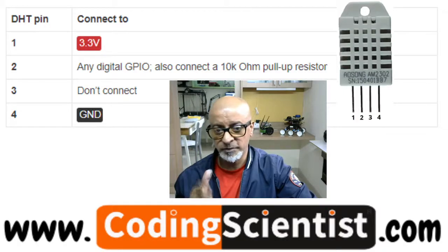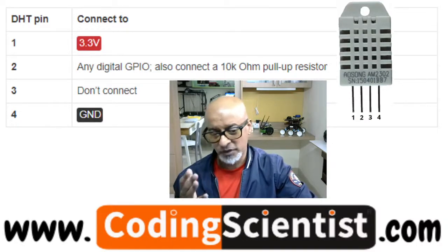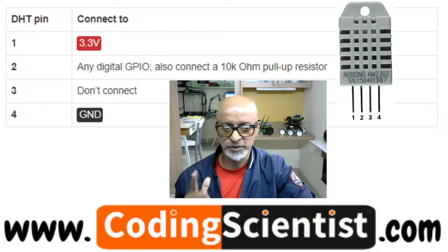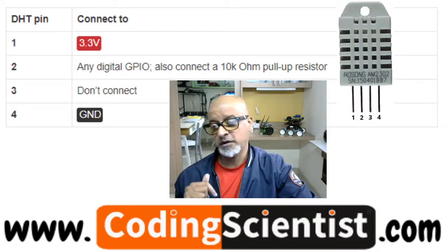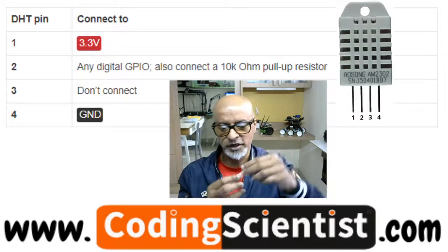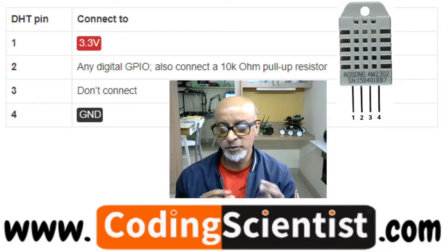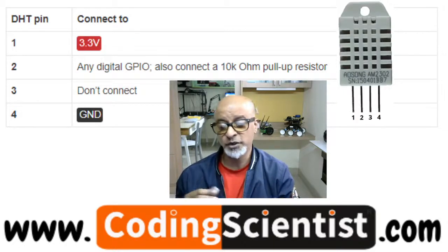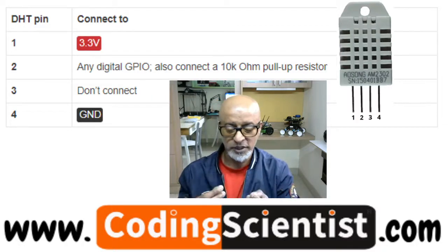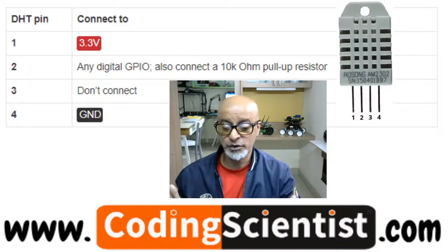If you look here at the pin configurations, the DHT sensor, especially the white one, the DHT22, has 4 pins as shown in this figure, just behind me. However, if you get your DHT sensor on a breakout board, like a module, it comes with only 3 pins and an internal pull-up resistor, otherwise you need to put in an external resistor. So that's what we are going to do in this lesson. I will show it to you.